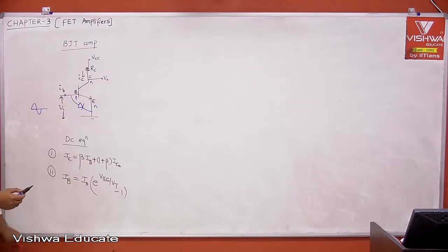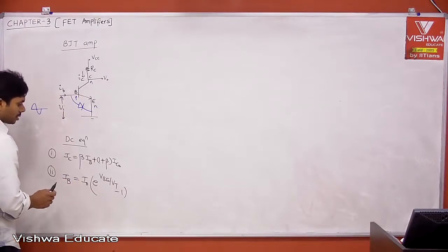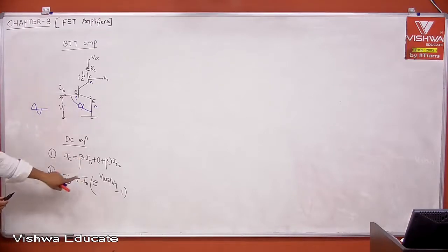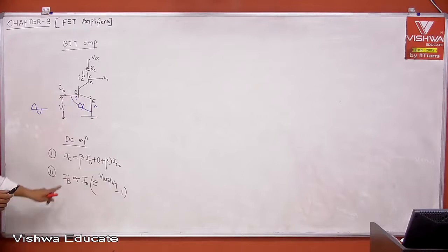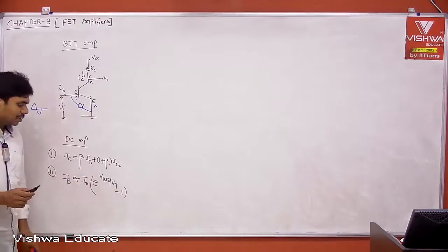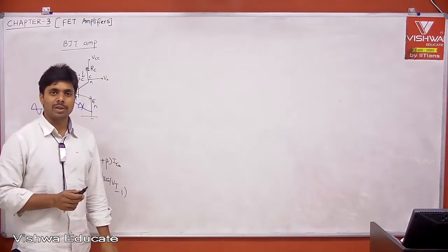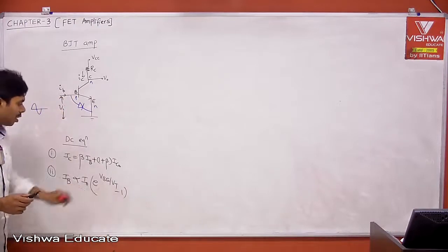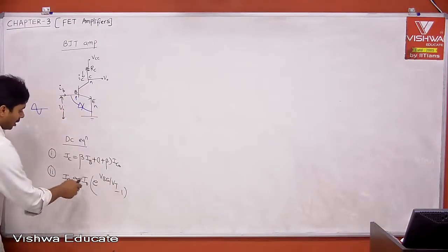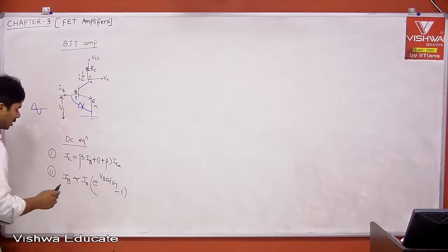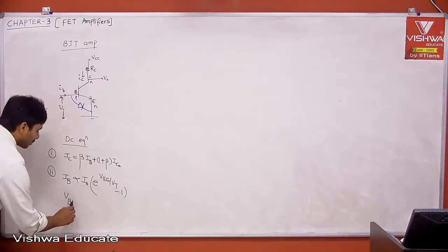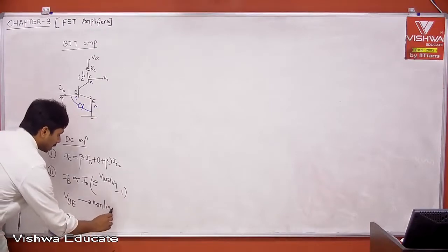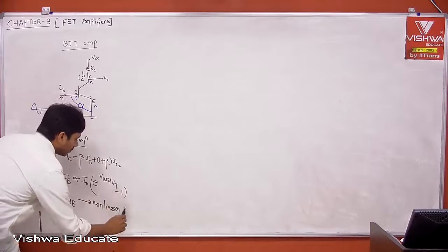But here, what is I0? That is what is different; it may be proportional to it, right? Therefore, now tell me what is the relation between IB and VBE? Non-linear. e to the power of x is 1 plus x square by 2 factorial plus x cube by 3 factorial plus x to the power of 4 by 4 factorial plus etc. Therefore, this is completely non-linear. The relationship between IB and VBE is non-linear. If you give VBE, you will get non-linear IB, non-linear IE or IB.